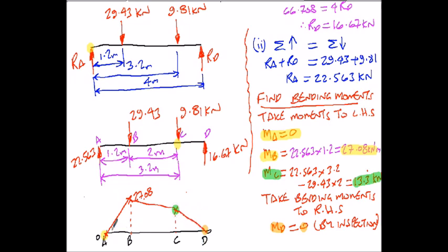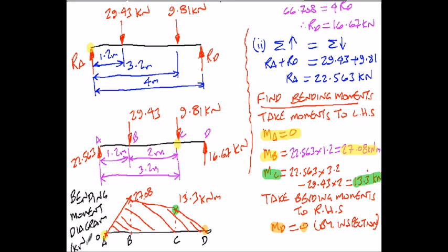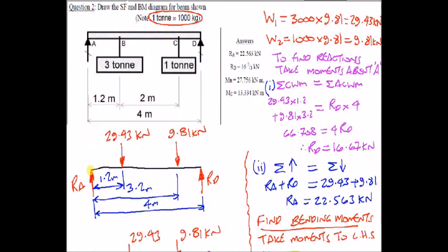Alright, so we're literally plotting the points on the bending moment diagram. Usually they're shaded in. Alright, so that point there would be my 13.3 kilonewton meters. Okay, so that's my bending moment diagram. And kilonewton meters, put the unit down, and if you want to be really clever, you put the bending moment rotation down. And that's job done again. Okay, so that solved our question 2.